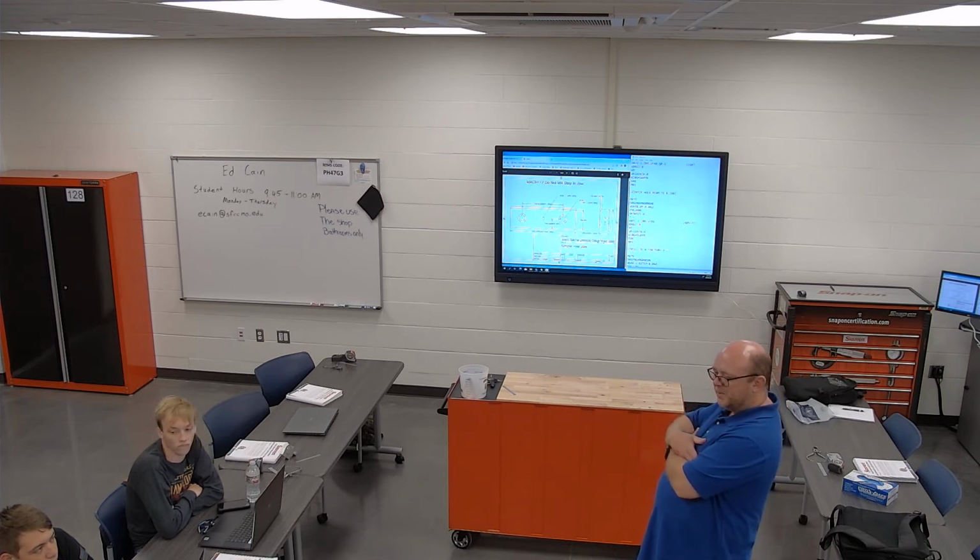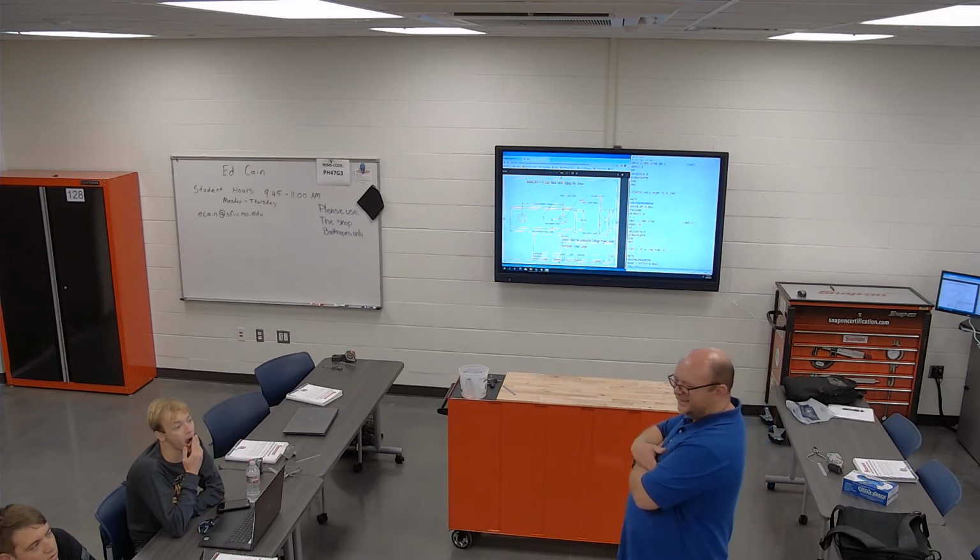It sounds like somebody was pecking too hard. We don't peck drill. We're not pecking at all. We just send it straight to the line, and that's what we do with all of ours, as fast as the peck drilling. There's a lot of stuff we're running like castings too. I would expect them to peck on Hastelloy, we just do 2/10 of an inch per rotation, just send it through. I know there is a deep hole cycle where it just barely bounces, just enough to break the chip. Yeah, but the program will put it that way, so that's the way we do it.